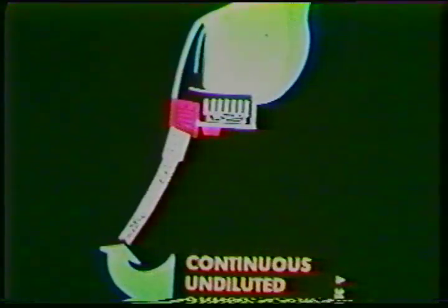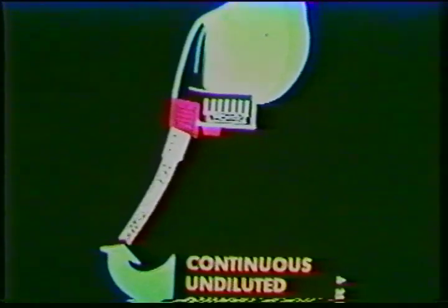A third supply mode can be selected using a rotary control in the emergency position. This position supplies a mask with 100% pure oxygen continuously, regardless of the position of the N 100% control.